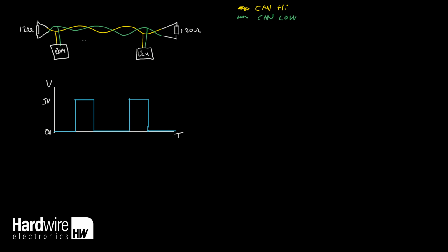Well, there are a number of good reasons why we use 2 wires on the CAN bus, and I'll go over more of them in a moment. But one of the main reasons why we use 2 wires and not 1 is that 2 wires helps us in terms of our resilience to electrical interference and noise. So let's look at this for a single wire setup, and if we get, say, a voltage spike here, like this, and we might have a voltage spike here, this can cause us big issues.